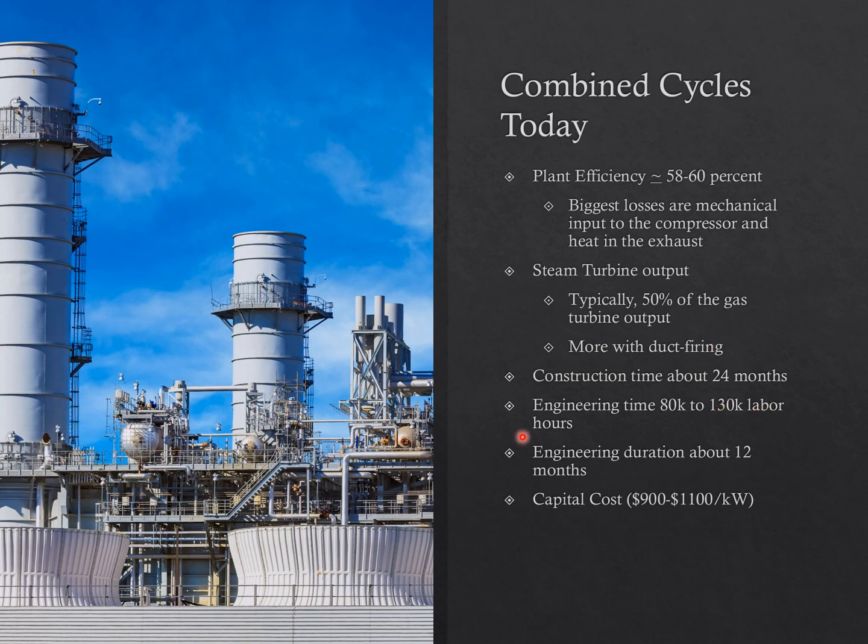About 24 months for construction time, and you have to put in about 80 to 130,000 labor hours, and about 12 months, so that's a year, for your engineering time. Money-wise, it's going to cost you about $900 to $1,100 per kilowatt. So that's your capital cost.